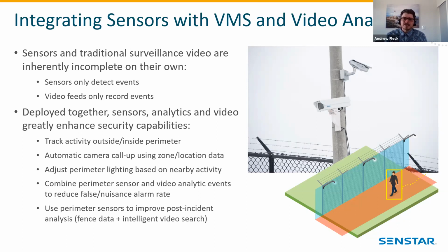So what we see right now is an example where the LM100 is on the fence as a line of perimeter detection. As well, maybe we're using a thermal camera, or potentially a standard fixed camera that's using object tracking to find people. We have a customer who actually runs the LM100 in a residential area at about 30% illumination during set standard hours where the sun goes down. They then use the thermal cameras or analytics to catch any type of motion in front of the fence, and then they illuminate the fence to 100%. This gives them the greatest capabilities that they have.